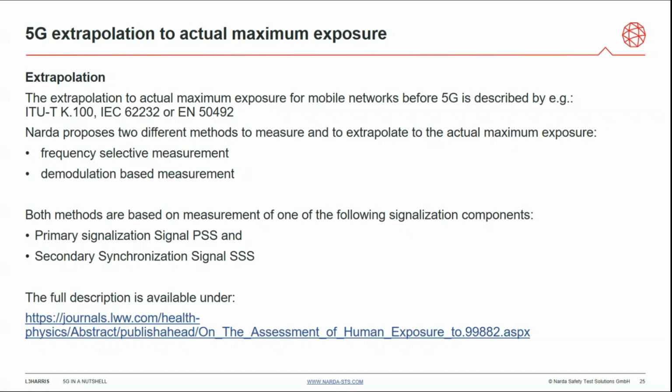to the users. So this method is there, but it's getting a little bit dodgy if there's too much traffic, because then the separation of the signal in frequency and time domain mode, so the respective synchronization signals which you refer to, are not that easy anymore.